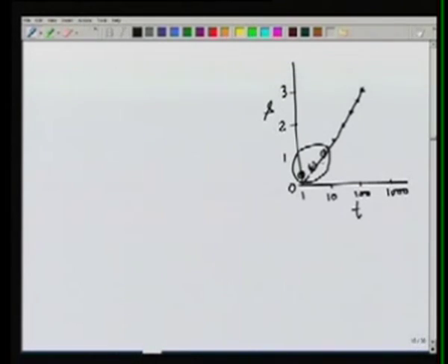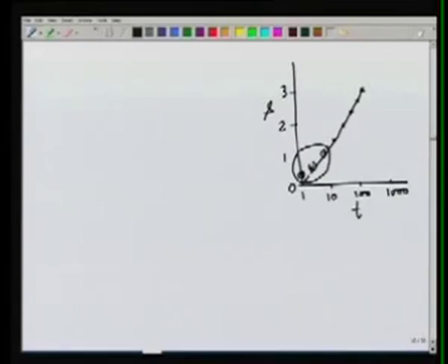This is because the time is small and therefore the u value is larger than 0.01. But once we see the data points falling on a straight line, we know that this data follows Jacob's approximation, and therefore we can use this straight line to obtain the parameter values S and T.